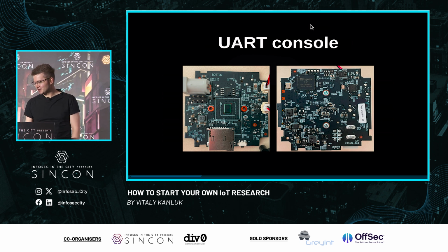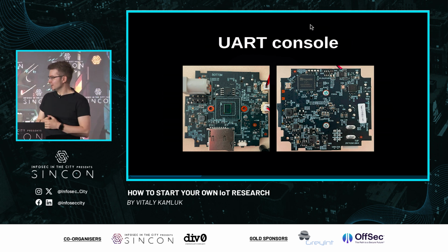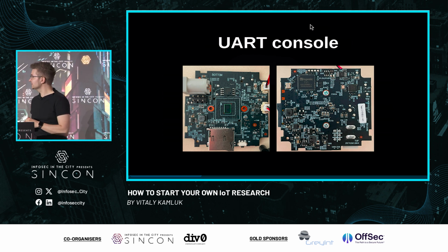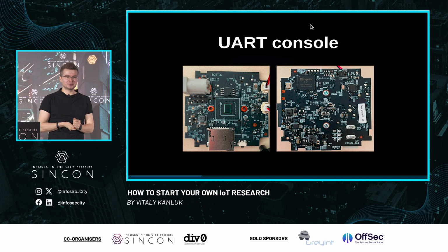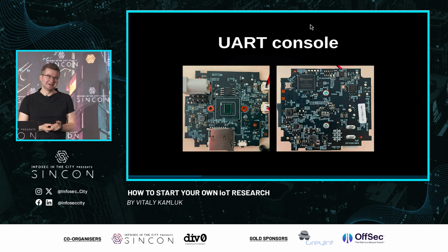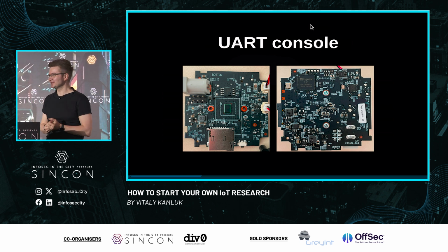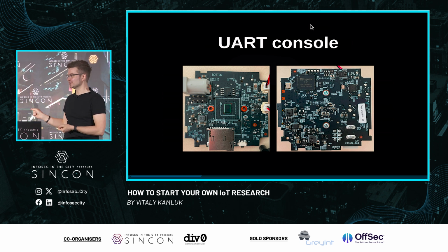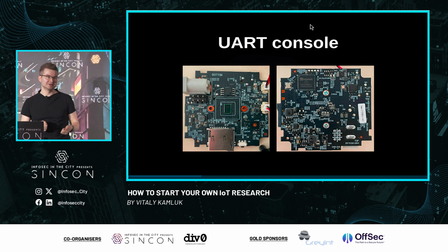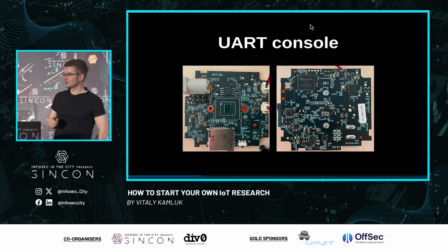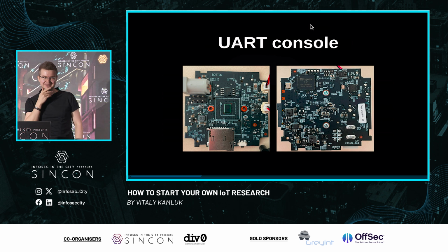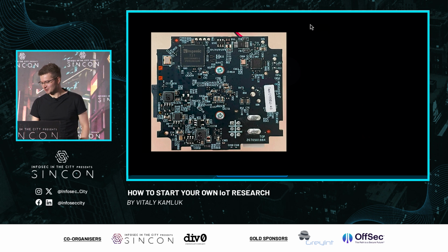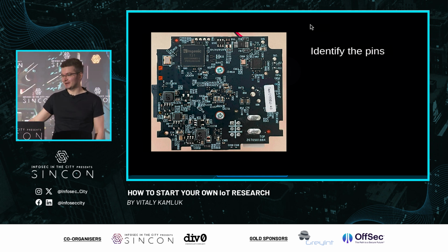So eventually I found, on the right image, on the top, you can see 4 pins aligned at the very top. So this was my guess. It must be UART, maybe. So how do you check that? You have to try. But to be able to interact with this, you have to know exactly what each pin means in order to connect to Tigard and then interact with this. Brute forcing all possible combinations could result in potentially burning the device, breaking it. So it is not recommended. You have to really identify the pins.